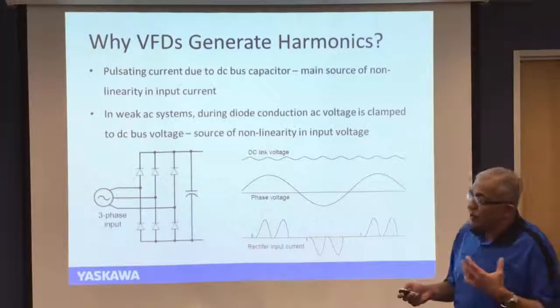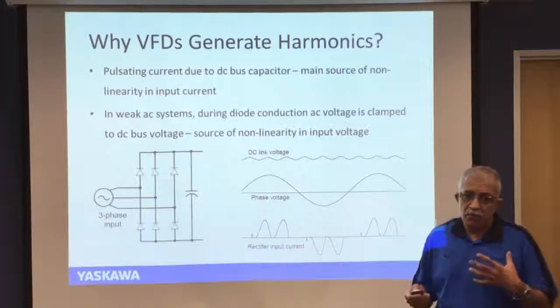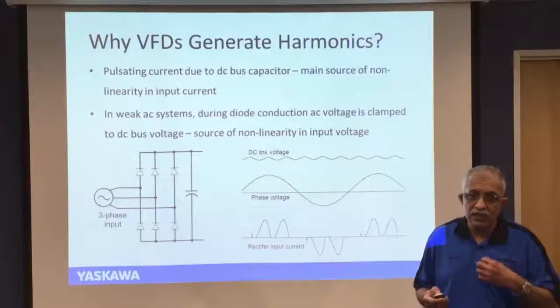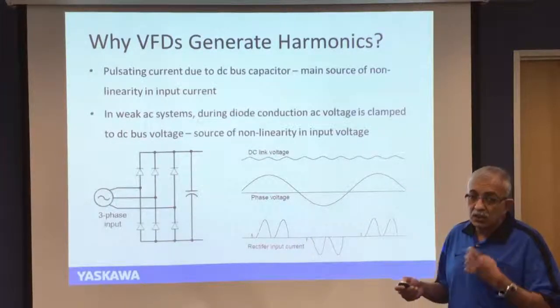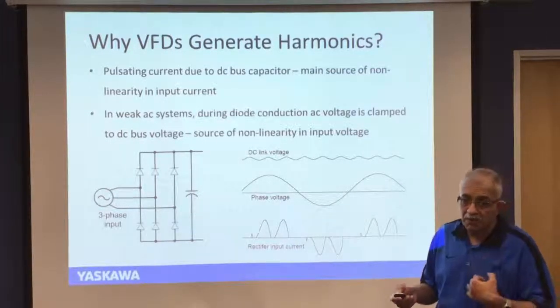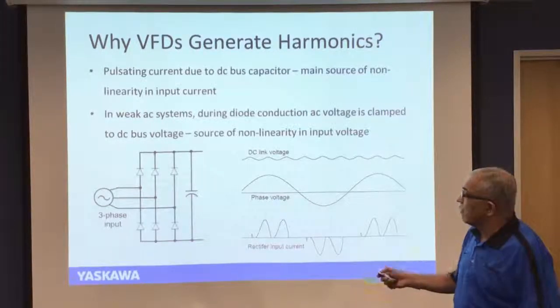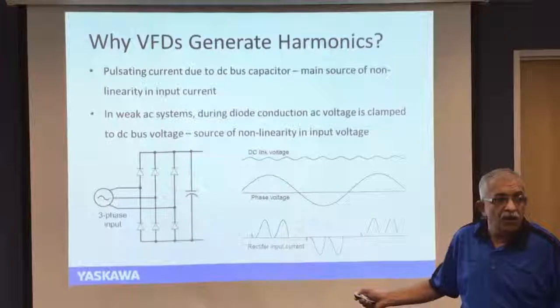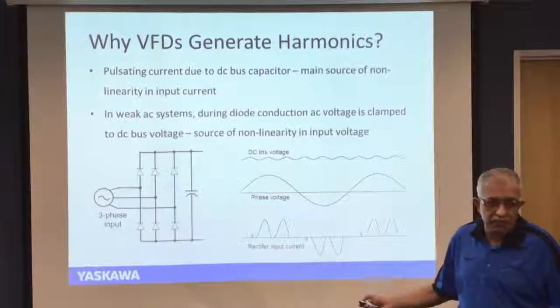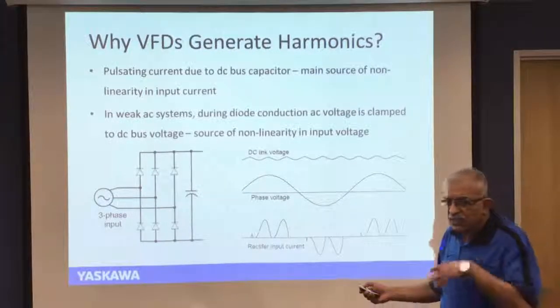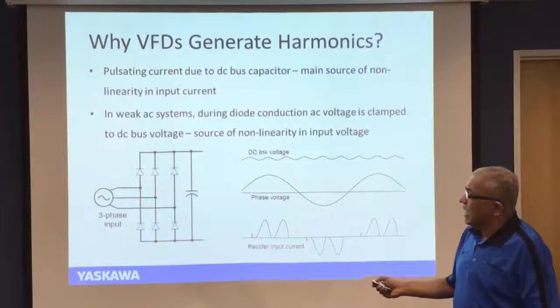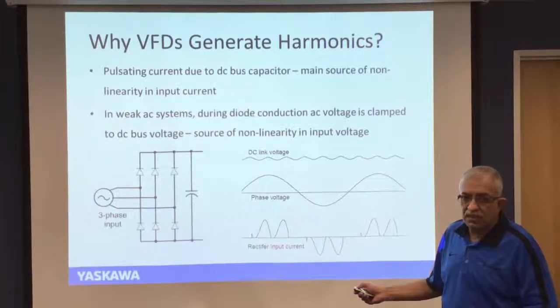Why do variable frequency drives, which are the workhorse of the industry, create distortions, or why are they responsible for creating distorted current waveforms? That is easily explained if one looks at the front end of a typical variable frequency drive. The front end of a standard variable frequency drive has a 3-phase AC to DC rectifier.